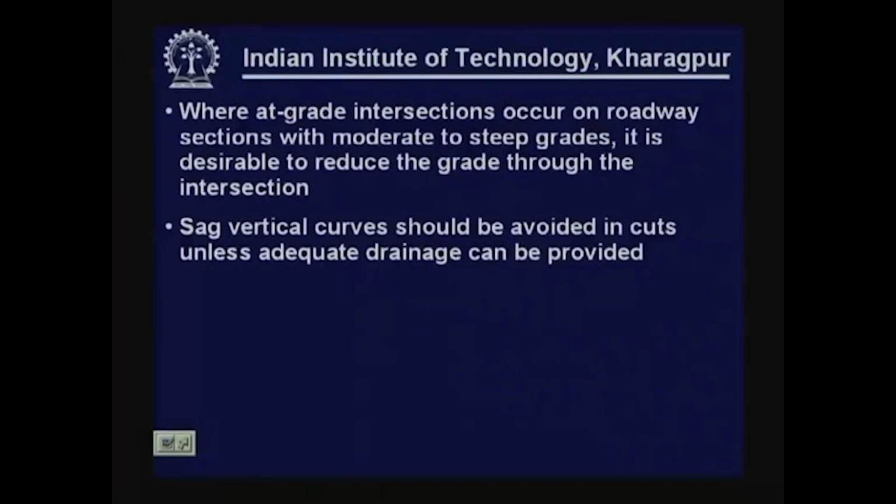Sag vertical curves should be avoided in cuts, needless to mention that, because obviously if we are using sag vertical curves in cuts, it will invite drainage problems. So, very special attention is required for drainage consideration.